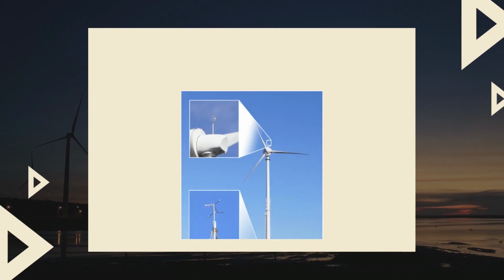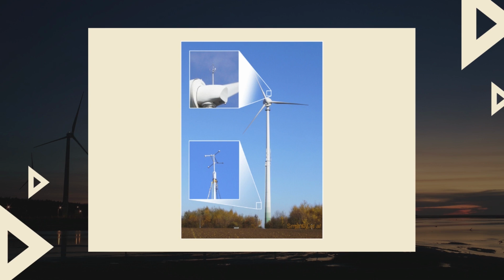Now, general setup needed for wind turbine measurement. Setting up to measure wind for a wind turbine involves a few important steps. First, we place anemometers, which are special devices that look like small propellers, at different heights on a tall tower. These anemometers measure the wind speed and direction of the wind. We also have wind vanes that help us figure out where the wind is coming from.